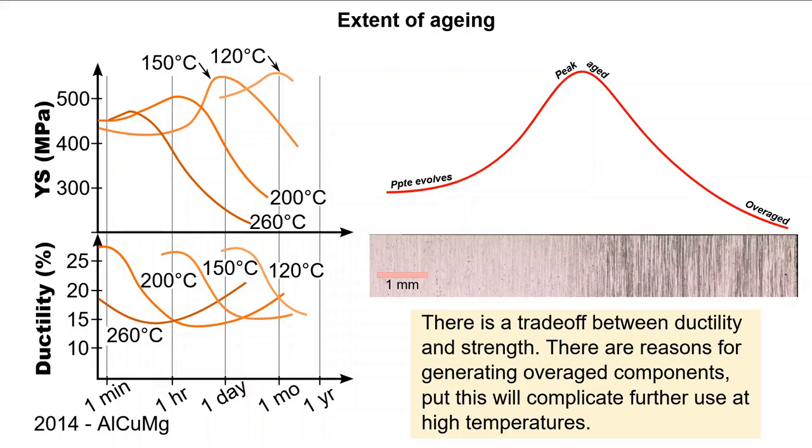For very large components, the entire aging curve can be observed microstructurally, as I've shown below for a thick aluminium 7075 plate. The larger the component is, then the harder it is to make sure that uniform conditions manifest throughout. So the strategy would be to maintain solutionizing and aging for longer periods of time, if costs permit.